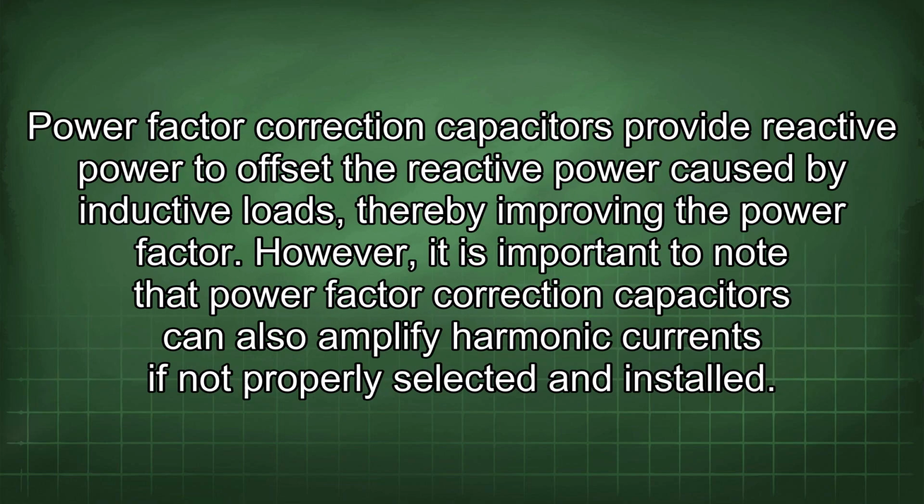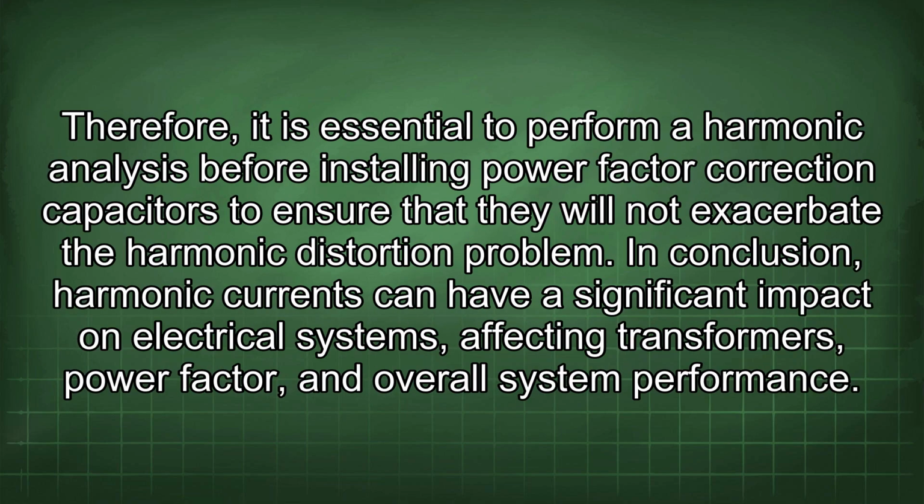Power factor correction capacitors provide reactive power to offset the reactive power caused by inductive loads, thereby improving the power factor. However, it is important to know that power factor correction capacitors can also amplify harmonic currents if not properly selected and installed. Therefore, it is essential to perform a harmonic analysis before installing power factor correction capacitors to ensure that they will not exacerbate the harmonic distortion problem.